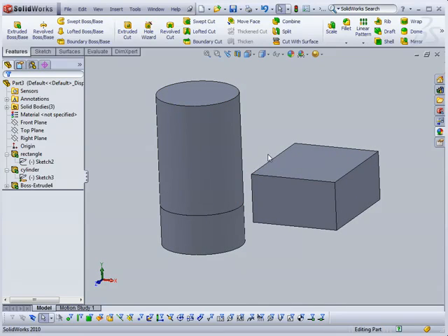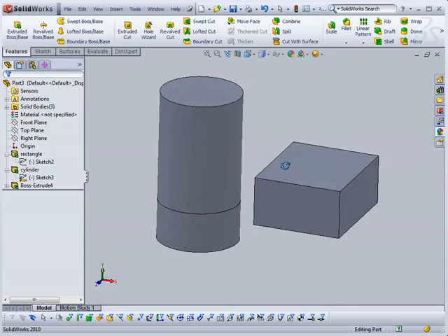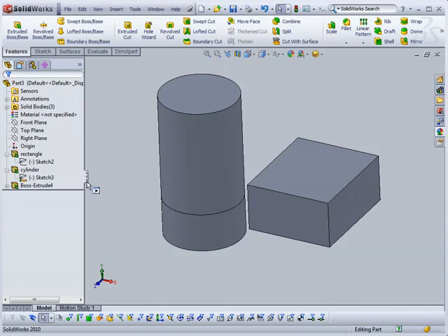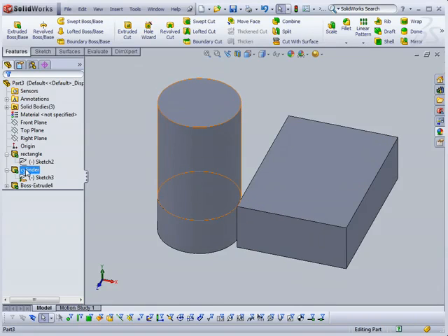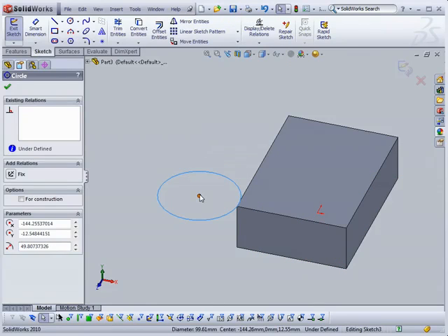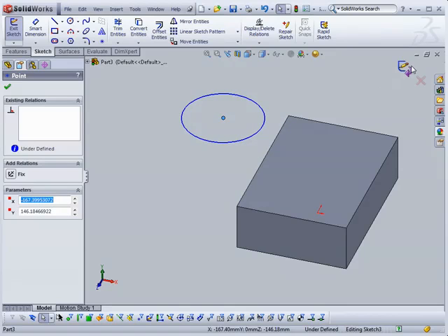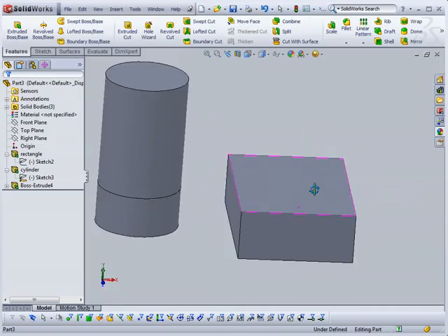So that almost covers it, except in my Rhino tutorial for the very first video, I show you how to move things up and down and left and right and move them around. Well, in SolidWorks that's a little more complicated. It's a little bit different. So if I want to move this box, the right way to do it and if I go here to my cylinder, I can move that by going Edit Sketch. I can click on my circle, and I can just drag it wherever I want it to be. So let's drag it over here, click OK. Now our cylinder is over there.